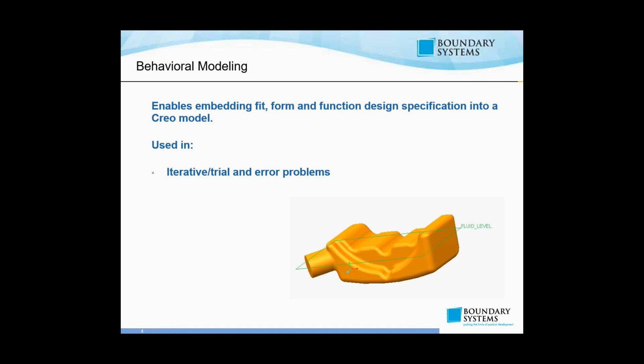in other cases, it could be mass calculations, it could be center of gravity calculations, it could be cost calculations as well. But your design targets can vary depending on what your application or your design is. But again, it's a matter of finding out what your negotiable design variables are, right? What are some of the 2, 3, 4 different dimensions or parameters you can tweak inside of Creo Parametric? And what's the optimal Goldilocks combination of those dimensions to where when you tweak them just enough, you're in your sweet spot where you hit your design target, right?